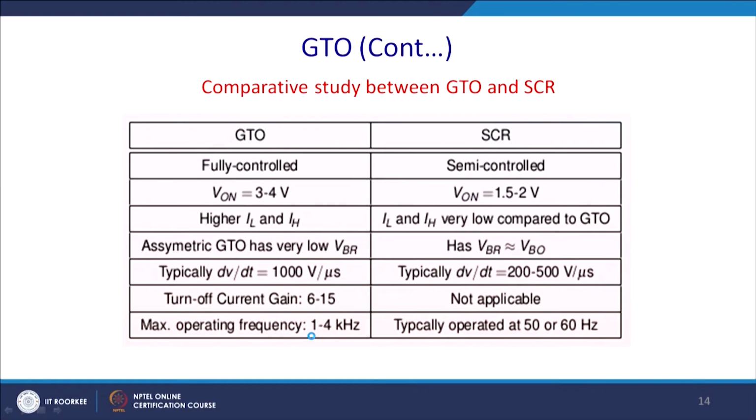So, what is the difference between the thyristors and the GTO? The problem of thyristor is that it is difficult to put off, except where you have line commutation in AC, where it is naturally commutated. Otherwise, you have to find some means to take the current through the thyristor below its holding current to put it off, either by having LC oscillations, which may require an auxiliary thyristor.